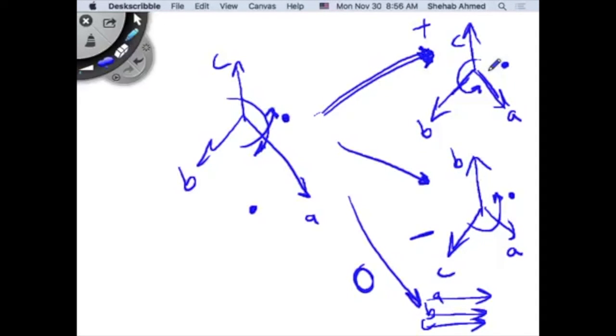So the motor will change speed. I mean, the direction of rotation will flip. It will be the opposite direction, right? So again, these three phases, what are they doing? They're creating a rotating field inside the machine. This rotating field, again, I'm not going to go through the theory of how to generate a rotating field, but it will rotate in a certain direction depending on the sequence of the supply. If you flip the sequence of the supply, the rotating field will rotate in the other direction and you will rotate in the other direction.